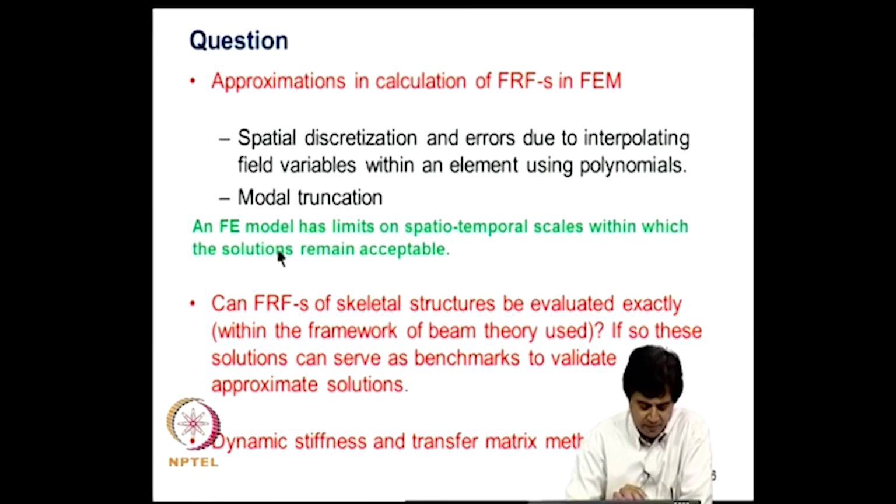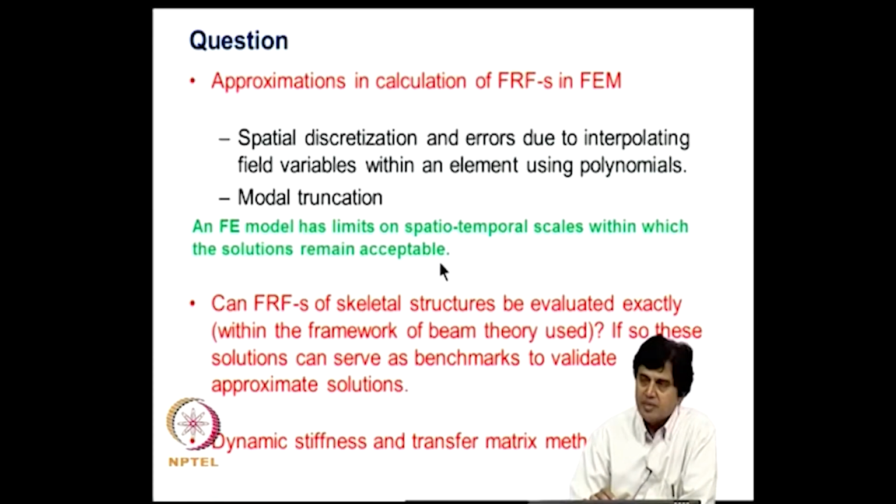So, this would mean that a finite element model has limits on spatio-temporal scales within which the solutions remain acceptable, right. A given finite element model cannot be used to resolve the field variables in space, there is a limit on that, and in frequency or in time.